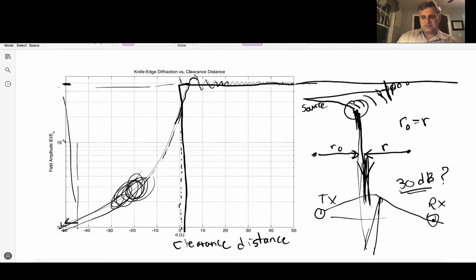And that sounds like a lot, but if you had, say, negative 60 or negative 50 dBm of received power, and you lost 30 dB from that, so that say you had now negative 80 dBm, dBm being decibels per milliwatts, then you would still have enough power for communications. That's plenty of power to get bits for a voice call or a data transfer reliably downloaded. So this is kind of the importance of modeling diffraction in some mobile radio scenarios, because there's often enough received power to still do what you need to do.